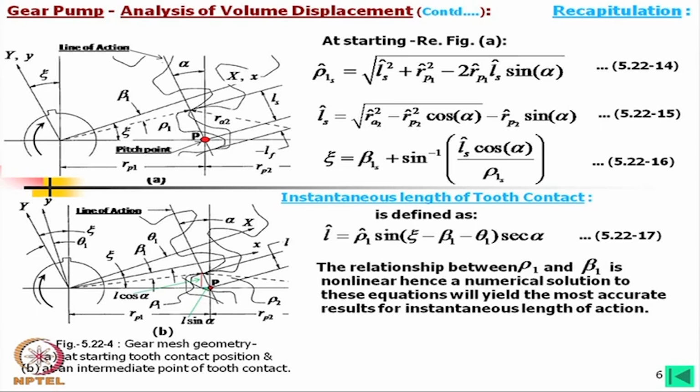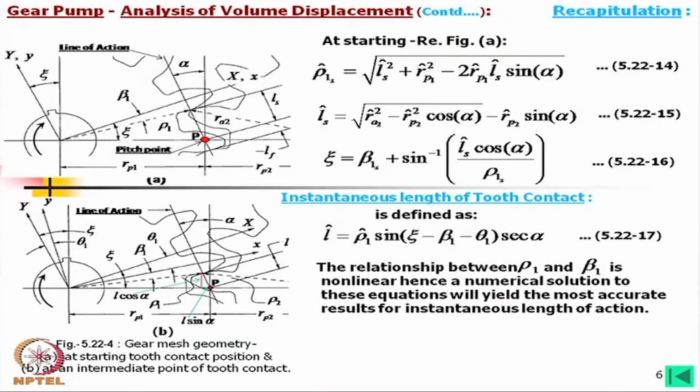But if we change the center distance, definitely this working pressure angle will change. Now, we should keep in mind, sometimes the teeth number is taken less than the allowable teeth number to avoid undercut, and in that case the working pressure angle changes.